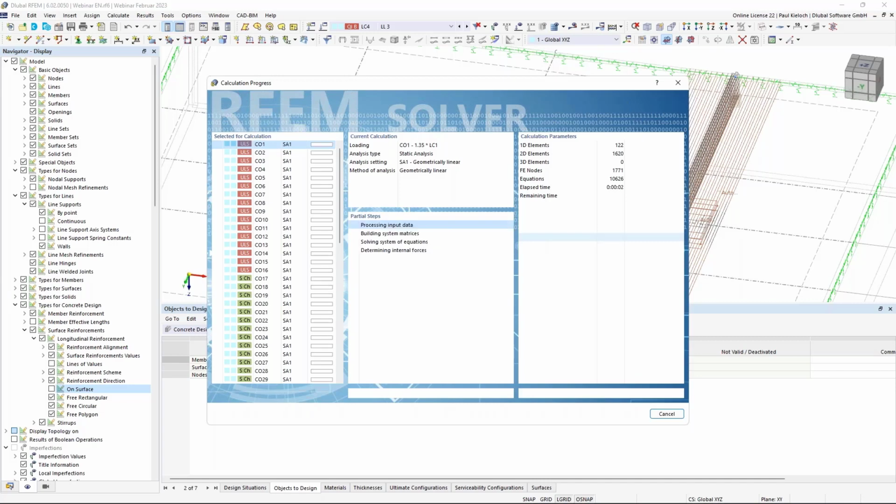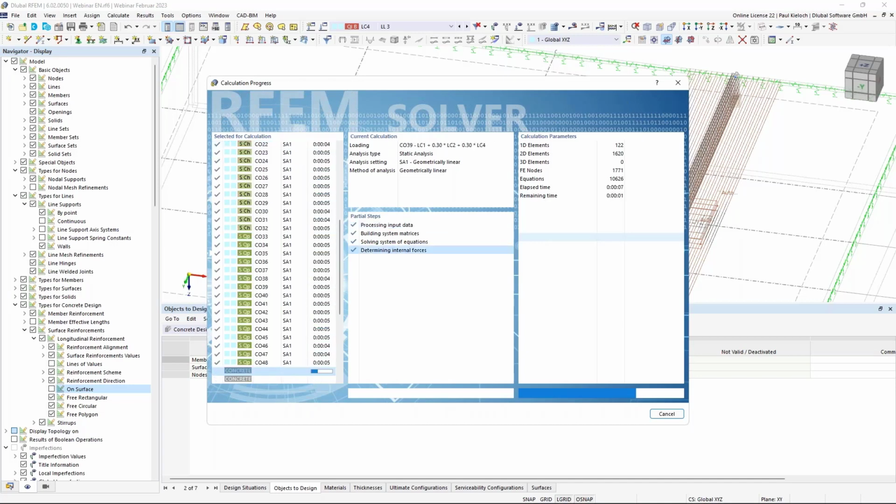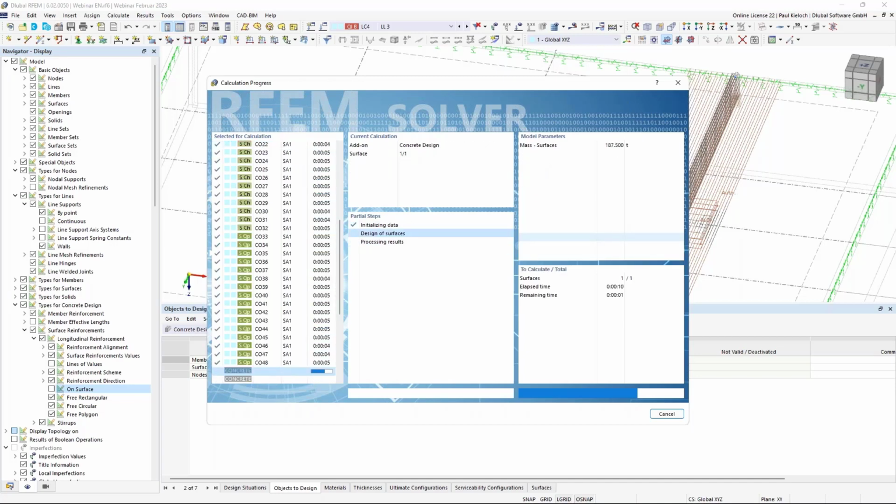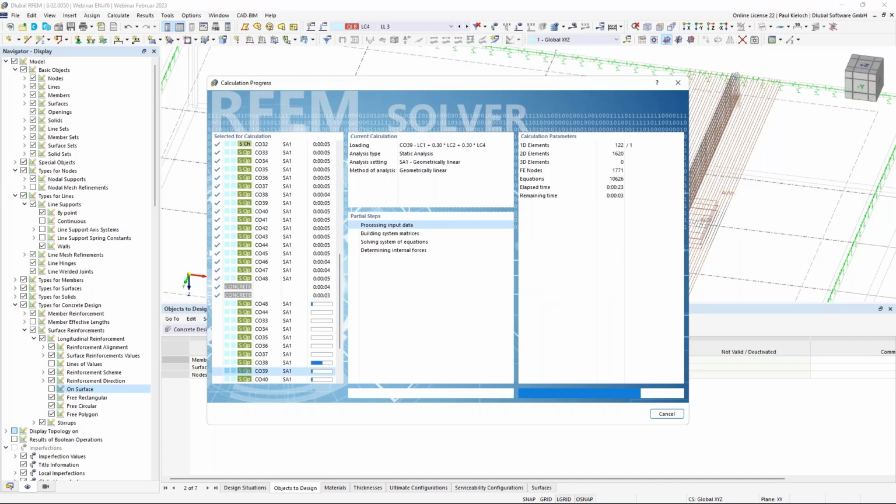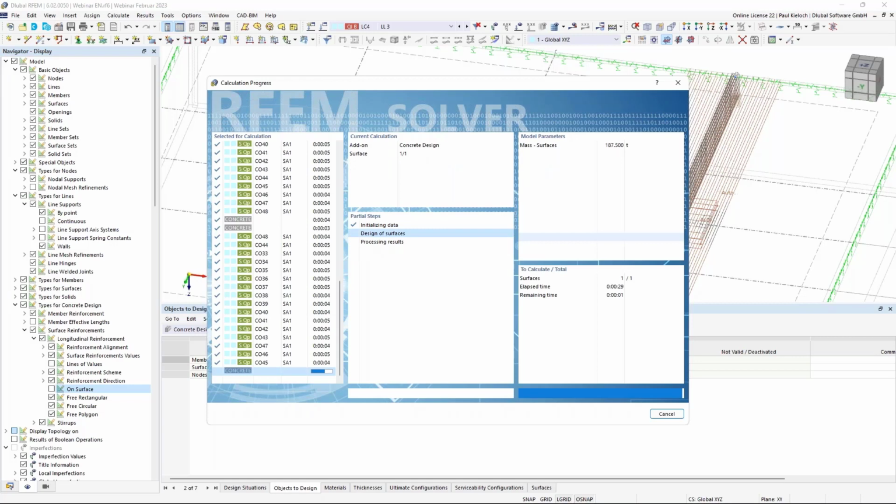And now the program will cover all the not covered reinforcement automatically, and the result will be that I'm getting an info about the spacing I have to use if I assign, for example, a diameter of 12 millimeter or 10 millimeter and so on. Maybe one point which I have not mentioned yet is that you cannot assign the auto function in diameter and spacing at the same time, so that is not possible. You have to use either the automatic function for the diameter or the spacing.